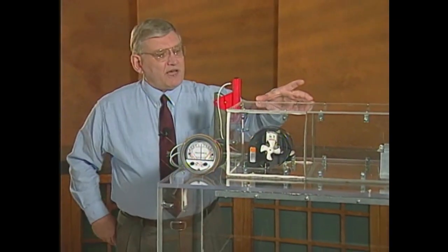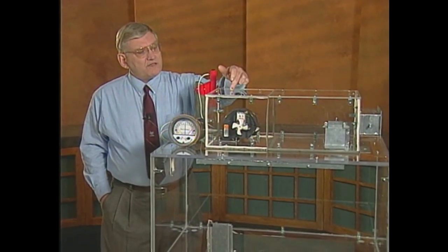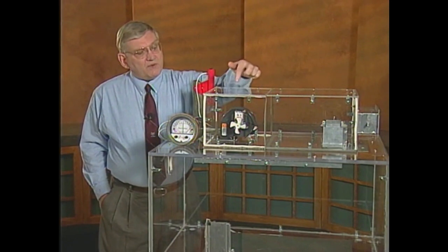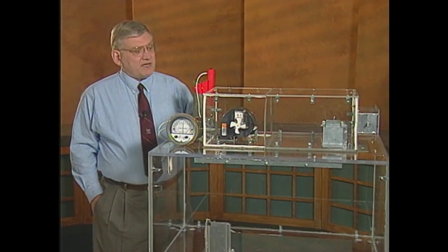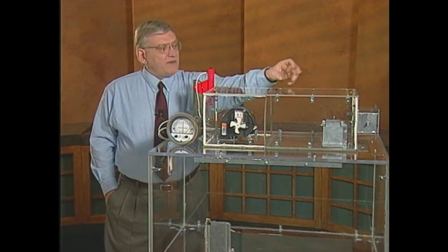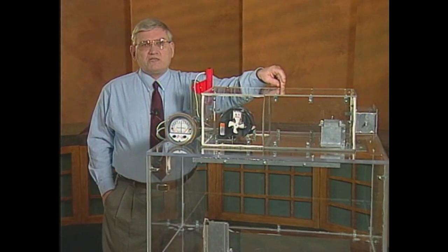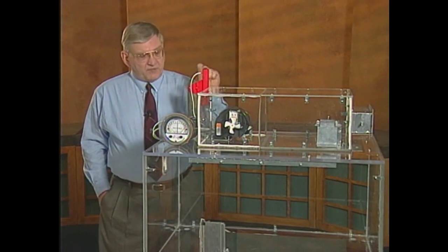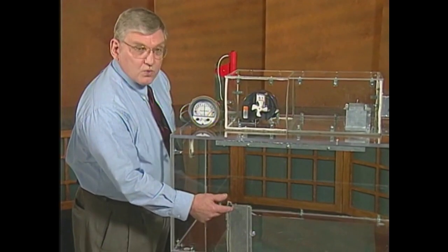On top of the building is an air handler, and we have two parts of the air handler. There's a supply fan section containing a centrifugal fan, and typically this would be where your coil and your filters would go. We left that little impeller that came on the front of the fan strictly so you can see that the fan is operating and how fast it's operating. The other section of the unit's replaceable. Right now we have a mixing box section to demonstrate a rather simple air handler. Later we can change this and make it a return fan or a central relief fan. In the building itself, we have a couple things to show you in terms of external appurtenances. One is a door.